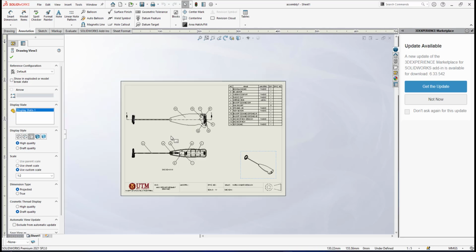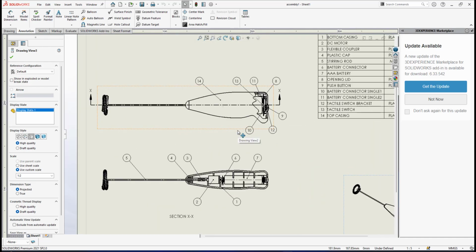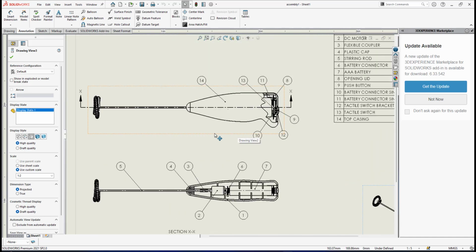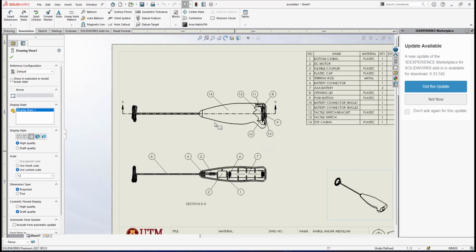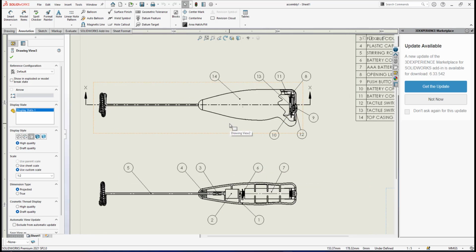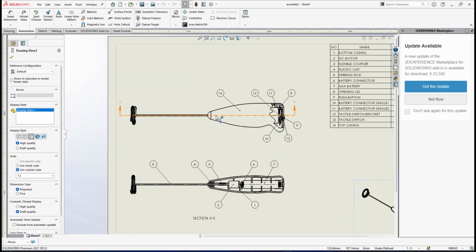Another thing about this assembly drawing: sometimes it's allowed to put dimensions in an assembly drawing, just for overall dimensioning. For example, when people want to read this drawing, they want to know the total size of this frother, maybe the total length, total width, and total height. So it's allowed to put dimensions in an assembly for general information, but we do not put detailed dimensioning.